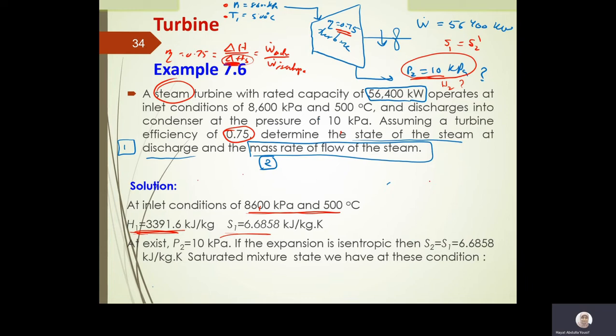All right. Of course, after you get the actual condition, which is delta H, of course H1 you know it. That's why we found it here. So if you have H1, then from the fact that delta H is H2 minus H1, and I do have already delta H, then I can find H2. Then at P2 and H2, you can define the system. This is the procedure. But let me show you how to apply that.